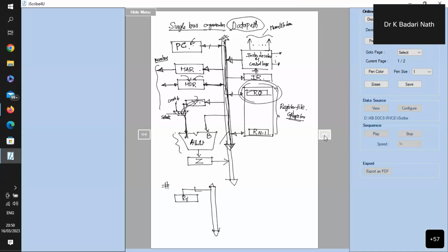That's why I'll introduce what is called a switch. What is a switch? A switch is nothing but an electronic circuit, a digital circuit, which acts like a close or open. How do we implement such circuits? There is what is called a buffer. ICs are available in the market. This is not an inverter; it's called a buffer. This buffer is also called a tri-state buffer. Tri-state buffers are extensively used in industry whenever we want to implement a switch-like feature.